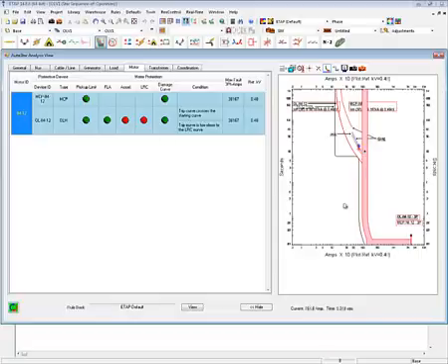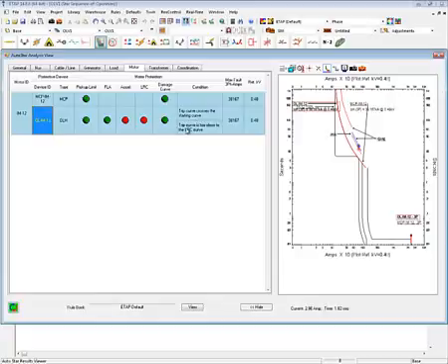As I adjust the MCP to a different setting, you can observe that issues have been cleared from the MCP, but we still have issues with the overload heater intersecting the starting curve, and that's what the software is telling you. The trip curve crosses the starting curve, and the trip curve is too close to the LRC curve.